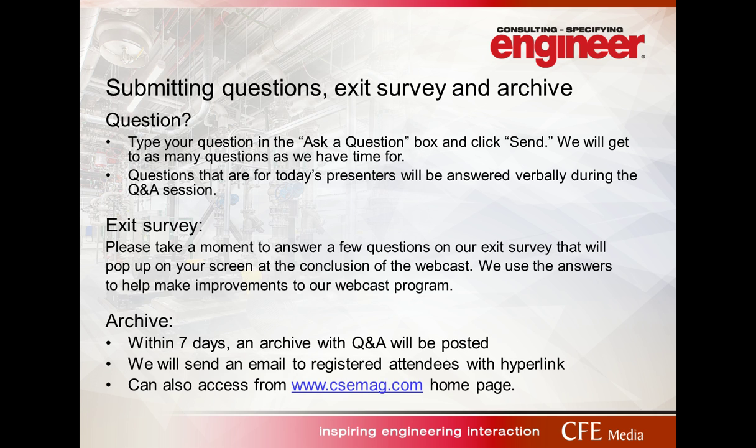Now, there are other systems where you're not reducing the quantity of ventilation, such as a heat recovery wheel, maybe an enthalpy wheel, or a plate and frame heat exchanger like Jeremy mentioned they used, that you can actually recover some heat or cool to provide pre-cooling or preheating of that ventilation air that is required via Standard 170, but not a reduction in ventilation itself.